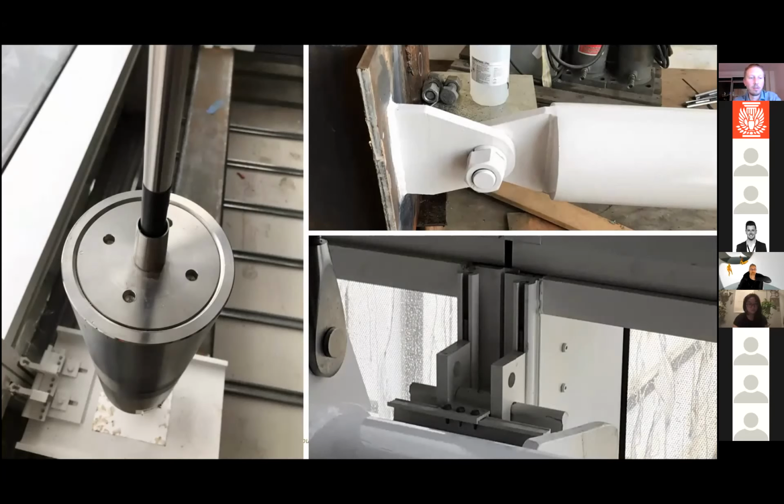So there, to the left, you see the spring. That's the bottom detail for one of those hanger rods, which is a cold spring inside of a housing that ensures that this rod will, because it's not a cable, right? It's actually a stiff member, but it's not supposed to ever go into compression, so that if that were to ever happen, then it would just bounce on the spring basically, and for the rest of the time stay in tension.